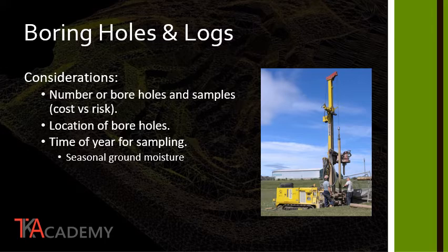The final consideration should be the timing of the year for which the sample was extracted. Subsurface soil information can vary depending upon the timing of the year. It should take into account things such as seasonal ground moisture, which is typically higher in the springtime.